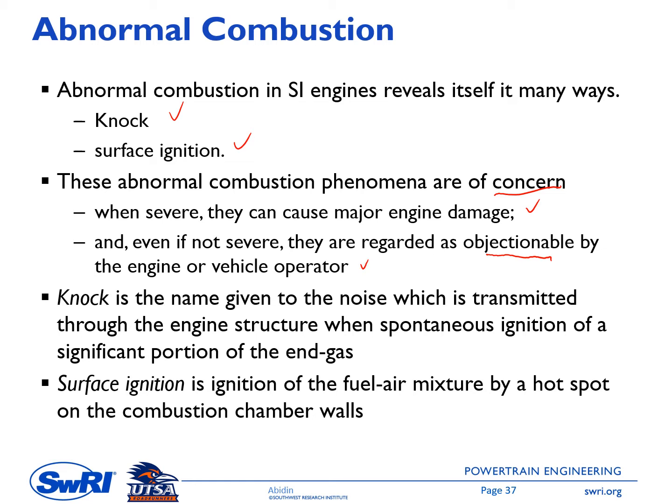Knock is the name given to the noise which is transmitted through the engine structure when spontaneous ignition of a significant portion of the end gas occurs. This spontaneous ignition occurs ahead of the flame front, so it adds energy release in addition to the energy release inside the flame front. And then surface ignition is ignition of the fuel-air mixture by a hot spot on the combustion chamber wall. It can be due to debris attached to the wall, and similar to knock, it adds energy release in addition to the energy release inside the flame front.